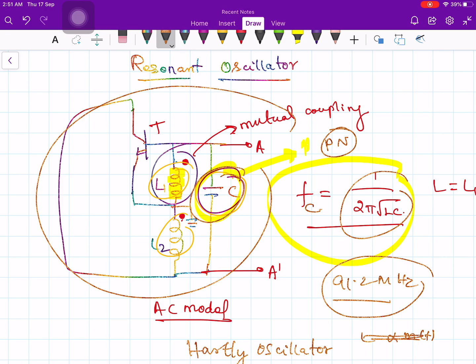Let's talk in terms of the factors that we discussed earlier. Namely, we consider two factors which were important when we discussed the indirect method: one was frequency stability, the other was distortion. In the direct method there is no distortion. If you have a perfect capacitance dependence like this, there is no distortion. We get a perfect FM signal in the direct method. Of course, for a phase modulated signal, instead of working with m of t, you will work with the derivative of m of t. That will be the only difference. So you can use the circuit for both the FM signal and the PM signal.